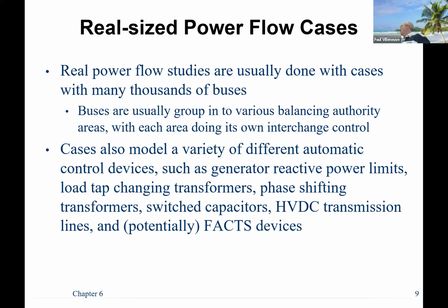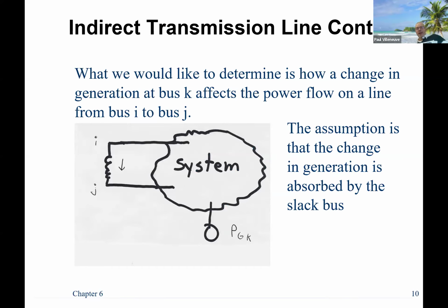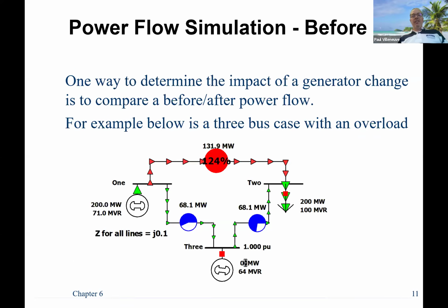We talked about HVDC transmission and flexible AC transmission systems, thus the static VAR compensator in Chester, which is about 40 miles from here. That's where you would see those smart devices. I think we already talked a lot about indirect transmission. So change the voltage, change a tap, and then hopefully you can get power flow to go in the direction you want. How do you know the power flow? The sensitivity analysis. How sensitive is a power flow change at bus 2 if you change the angle theta 3, theta 36? You can look at that with sensitivity analysis. And again, it's just one big box, right? You don't have direct control, so you're trying to monkey with things as much as possible.